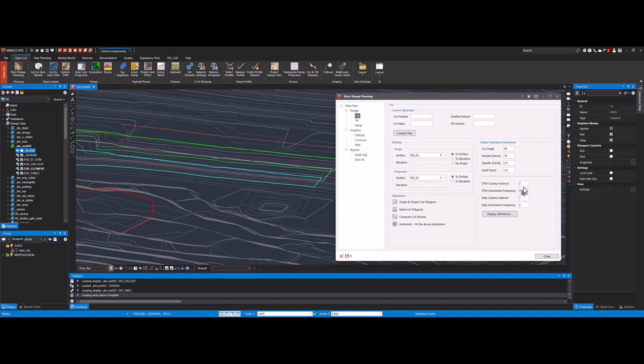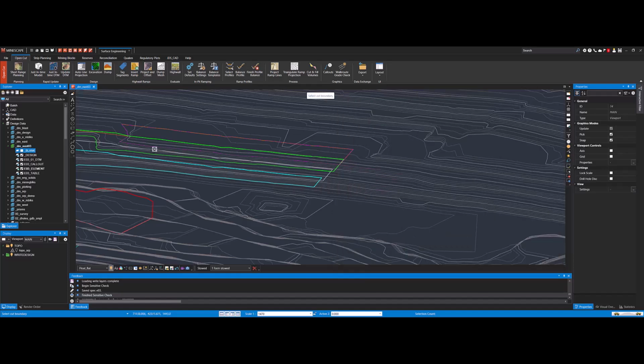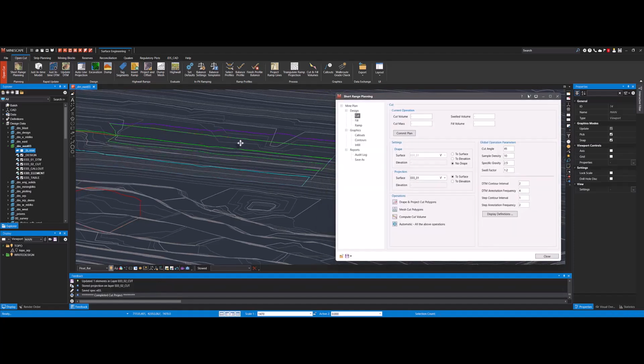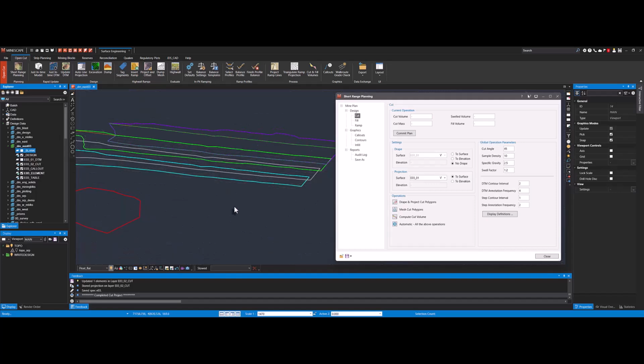First, you create detailed excavation plans for cut areas. Next, you move into dump plans, which are handled step by step to ensure balance and accuracy. Finally, you design ramps and benches, and the tools automatically check for gradients and smooth connections to existing surfaces. Because the SRP tools support front-end setup, you can do much of the preparation work up front. That means when you get into detailed design, the process is faster and more efficient.